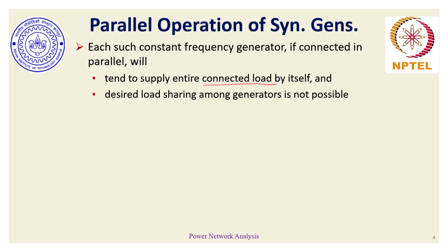So it is possible that the economics might be ensured through economic dispatch, but economic dispatch, as we have discussed, was for an hourly generation, or a period of time where the load is not changing, and that particular hour was considered to be one interval. But as we also understand, the load is not a stagnant quantity, it keeps on changing.